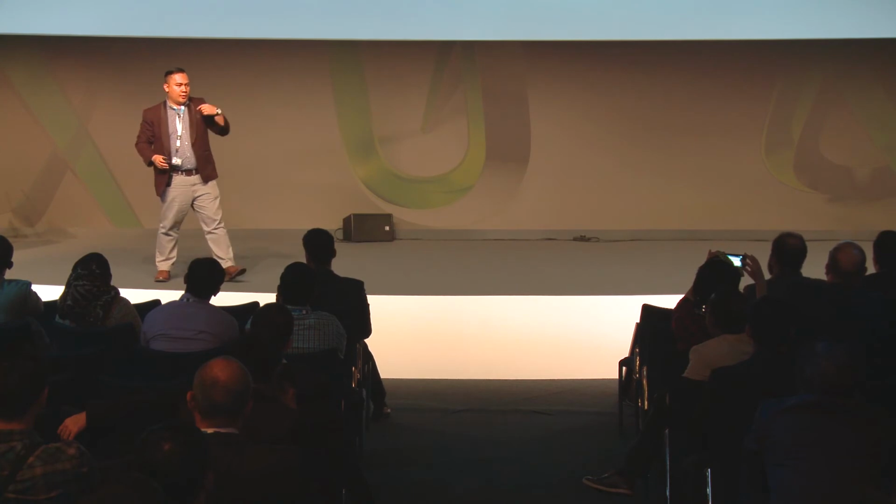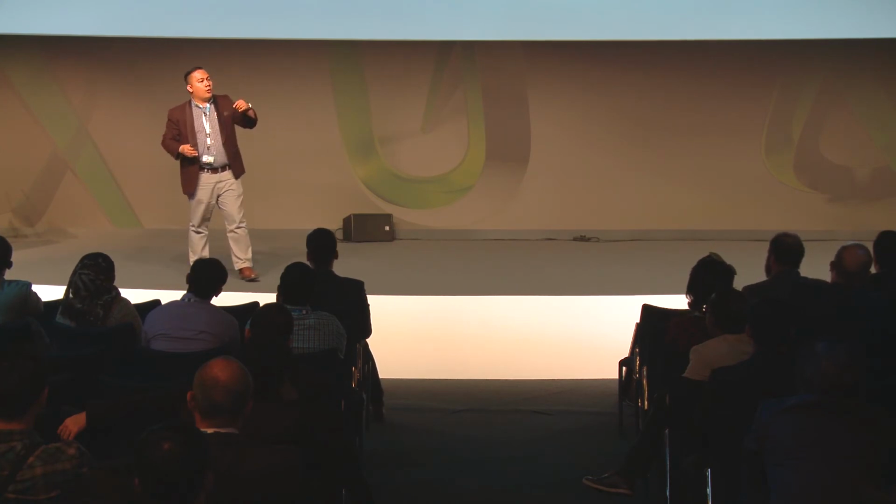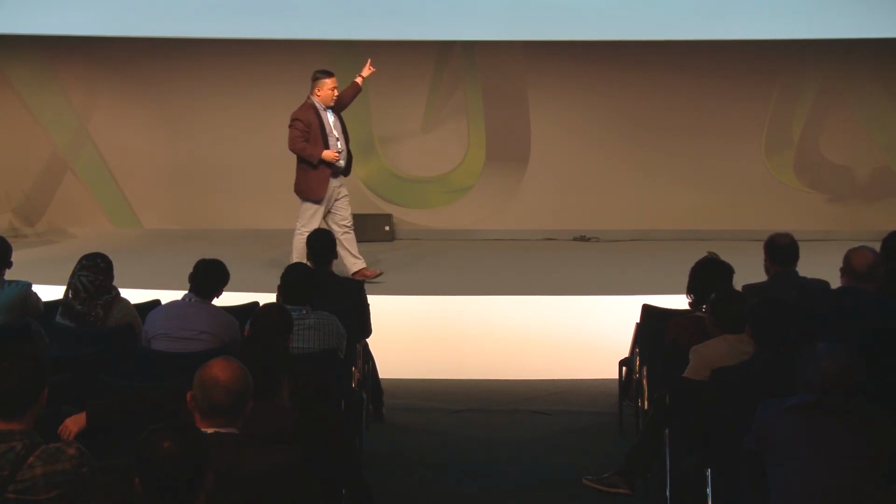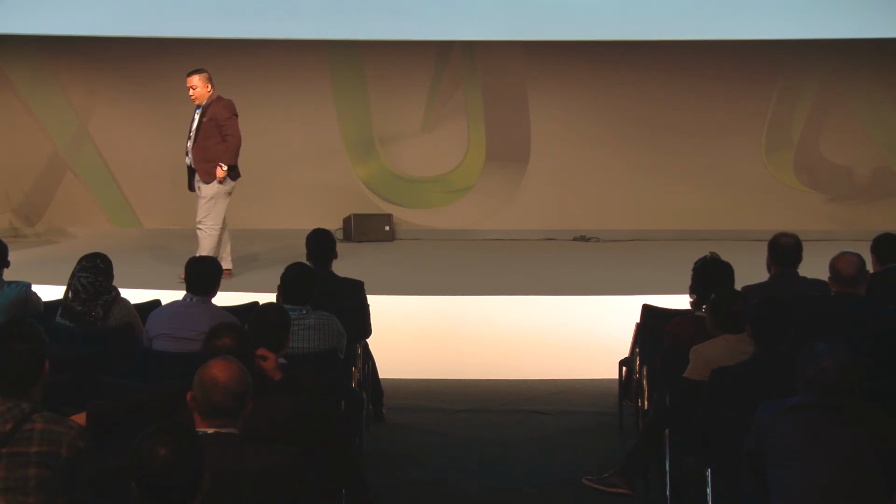If you are a contractor, and you pass to me a drawing or a model for the ceiling-mounted projector, and you pass to me a 2D AutoCAD representation, it's okay with me because you actually fulfill the requirement at LOD 100. So when we go to LOD 200, you now begin to see that the level of detail of this ceiling-mounted projector begins to have shape and volume, right? But still it is unrecognizable because at LOD 200, it is still grade 1. So again, as you can see, there is an added level of information there.